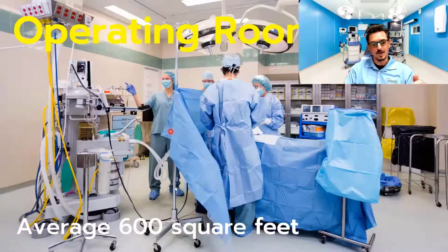So the average operating room is 600 square feet today. Apparently it used to be 400, now it's bigger. There's a lot more stuff in there. This is a typical operating room. You got a lot of people in there, a lot of lights, maybe some extra filtration. There's a lot of stuff going on in these small spaces. And I would guess an operating room like this would probably be about 5 or 6 tons of AC just for this room.